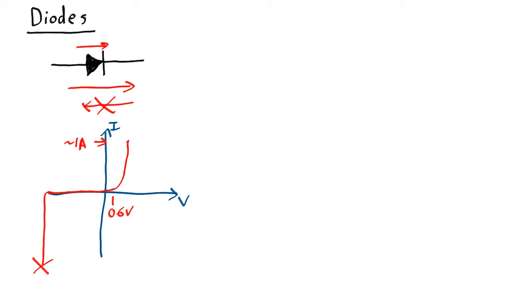However, there is a particular type of diode called a Zener diode, where this behavior over here is actually deliberately used. So Zener diodes are much like normal diodes, except they're designed so they don't melt in this particular situation unless you make the negative current too large.